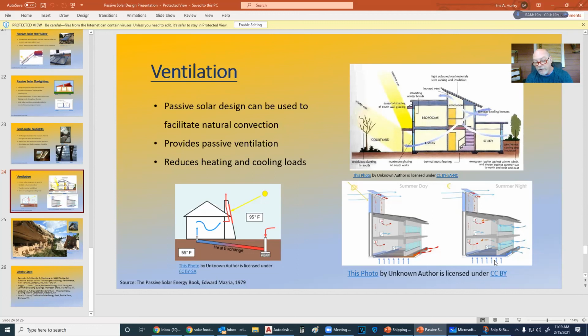When cold air sinks to the ground, it can come down the chimney, so you can have a backdraft. That's why sometimes you can have problems in really cold weather if the chimney is not built correctly. If it's just a plain old solid shaft up through there, cold air will actually backdraft down through there and blow the smoke into the house. I've seen that happen several times, just because a smoke shelf or the throat of it has not been put in place. That's what the throat is for, to help prevent that backdraft. And we have reverse induction in this climate also.